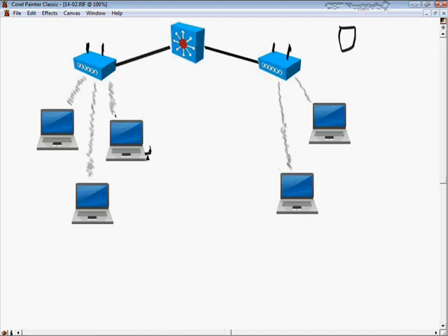Now, obviously, because of wireless, objects can cause different types of interference. Reflection occurs when an RF wave bounces off an object, let's say a planter that has plants in it, or an elevator shaft, things like that, metal or glass surfaces. We can have scattering when the RF wave strikes an uneven surface, for example a rough surface, and absorption when the RF waves are absorbed by objects, for example walls and carpeting.